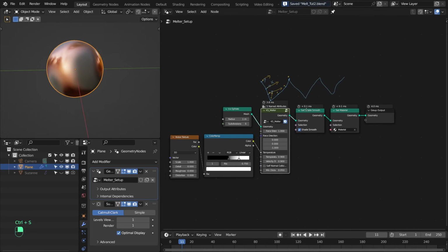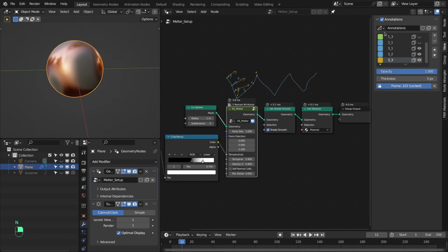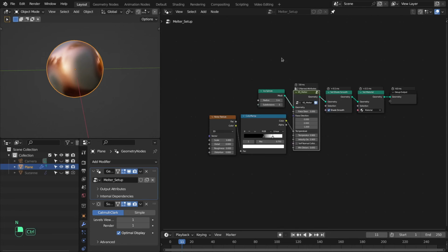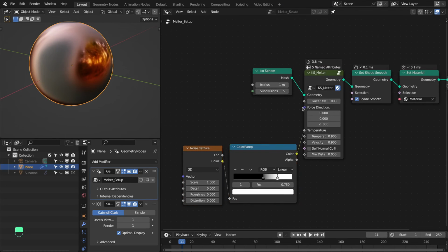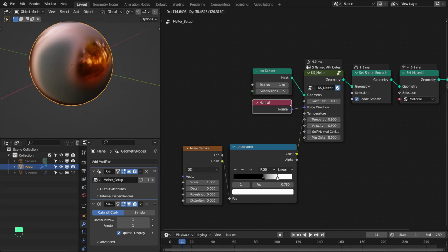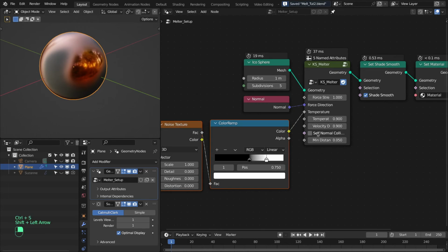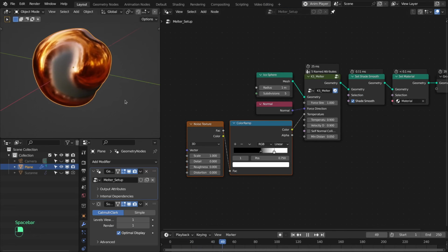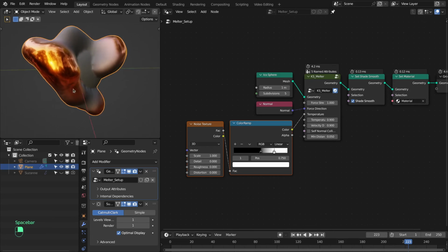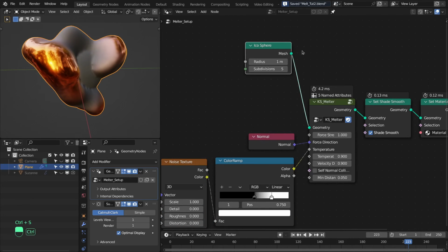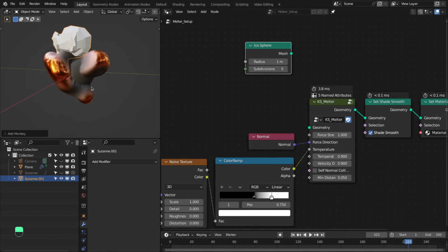Because we are checking this along the normal of this mesh, this collision mechanism works well when we want to inflate this object. Add here a normal, so we are making the force direction along the normal of this mesh. Let me first do this without the self collisions. There is no collision here. Let me change the mesh to a monkey, so that it is a more complex mesh.